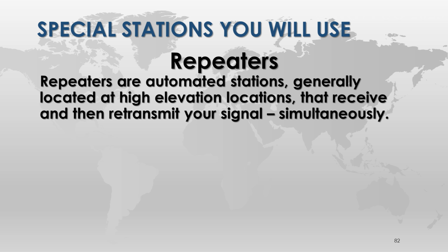So the repeater can only do one frequency though? One frequency pair, separated by some frequency distance. Yeah, so on 2 meters, we have a 600 kilohertz separation. So when I tell you that John's Peak is 147.100 positive offset, tone 136.5, 147.100 is what you dial into your radio. The positive offset is shifting 600 kilohertz up, to a higher number. So 147.100 is what's in your radio, but when you key up, it transmits on 147.700, 600 kilohertz higher. And when you let off, you listen on 147.100.